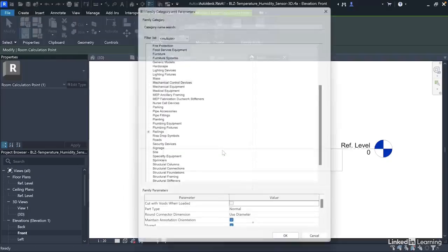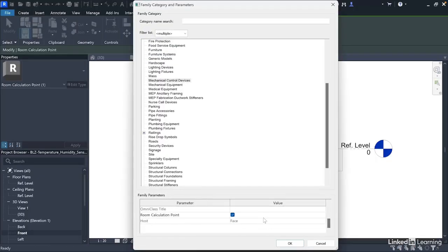Then when you go back here, you also see the hosting or the host. The read-only status validates that you cannot change the hosting method, and that is why it's one of the first considerations when creating a family. Unlike category, you can't change the host of a family later. Again, the parameters differ a bit depending on the family category, but these are some of the most important ones that determine the behavior of Revit families and projects. These are the crucial considerations for starting a mechanical family. In this chapter, we'll create two families, one terminal component and one equipment.